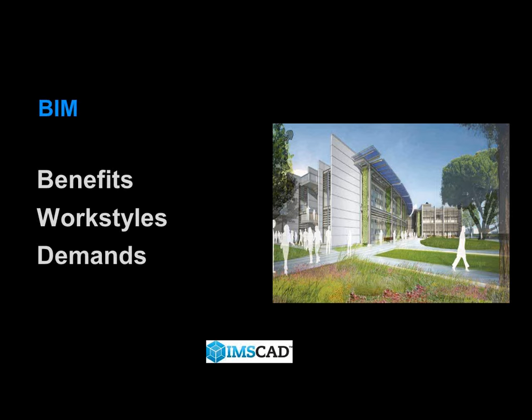Now, to do this, the model is based on a combination of what we term objects: generic, product-specific, solid shapes, and indeed void spaces. They each carry their own geometry, attributes, and relations. And it's the objects' defined parameters and relations to the other objects that automatically determine, when one is amended, what impact it will have on the other dependent objects. So this dramatically affects the impact of any change on all collaborators, their services, products, and obviously as a result the basic work styles of those contributors.